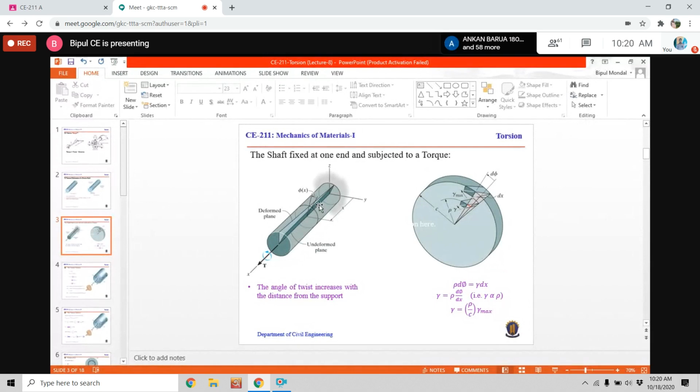Okay, so there will definitely be a shearing strain, because we know what shearing strain is. Shearing strain is the angular change, right? Shearing strain is the angular change of a plane or of a line. So as the plane was there, look at the second figure, and this plane has come here, so there will be an angular change. That means there will be a shearing strain.